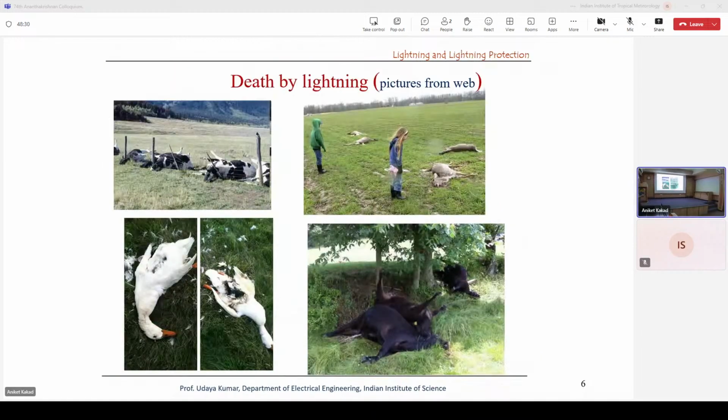And this very sad-looking picture has been inserted intentionally for two reasons. One is, lightning could have been elsewhere. The induction to the fans would have caused a serious shock because the human body is so susceptible. It needs a few milliamperes to pass through the heart region to cause a cardiac arrest. So you don't need amperes of current. So induction is somewhere, activity somewhere else.